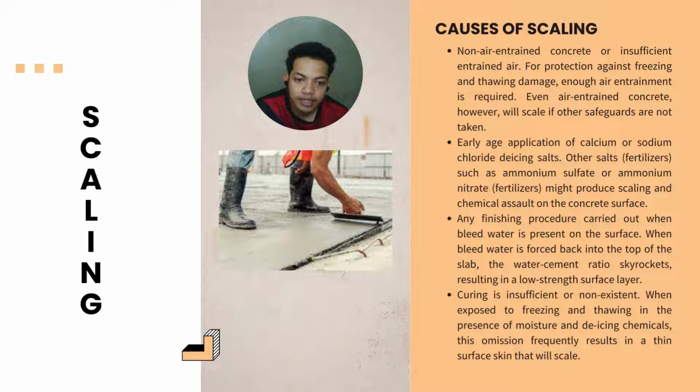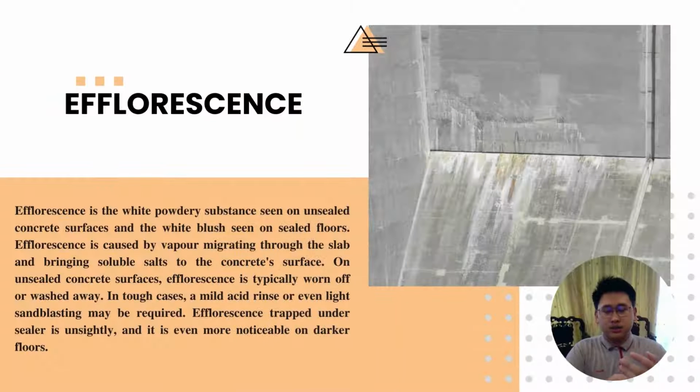Curing is insufficient or non-existent when exposed to freezing and thawing in the presence of moisture and de-icing chemicals. This omission frequently results in a thin surface skin that will scale. Next common root cause of a concrete problem